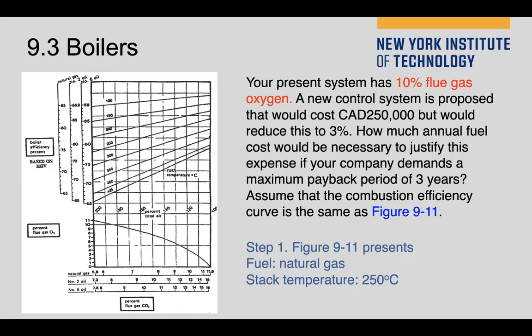Okay, thank you so much. You're welcome. So any question on what I explained about the flue gas percentage? And then you have a concept: why does this show a high percentage of flue gas oxygen? That means it's not good. If we can lower it down, we have a higher efficiency. That is where we need to invest the money. We have this story of saving.